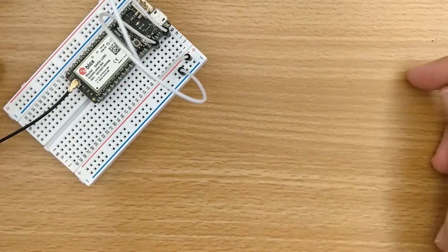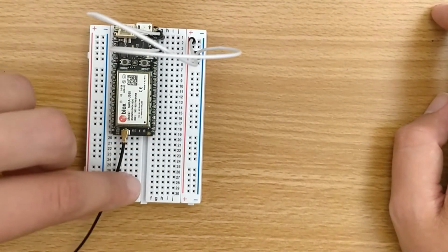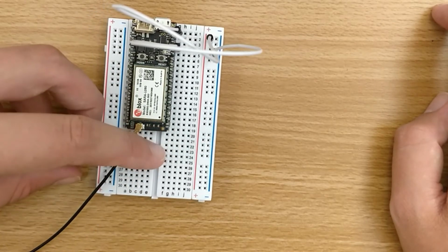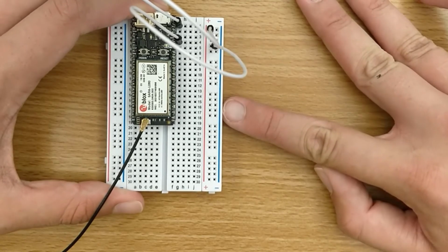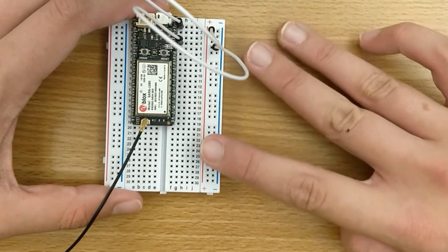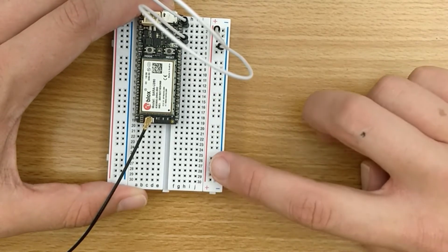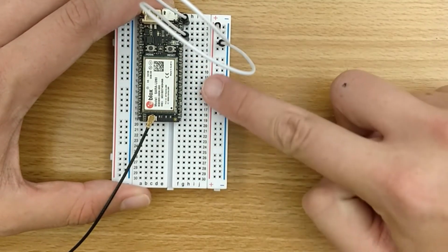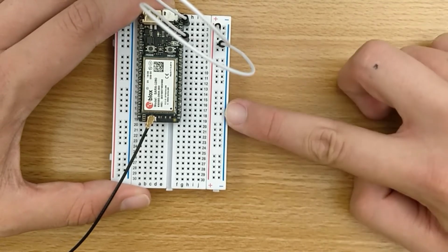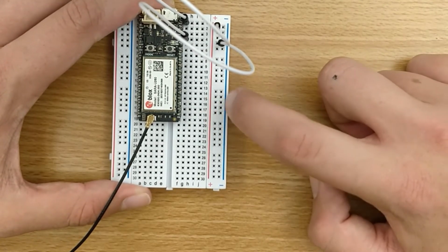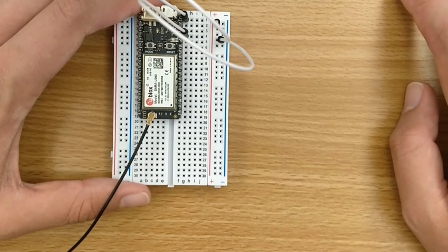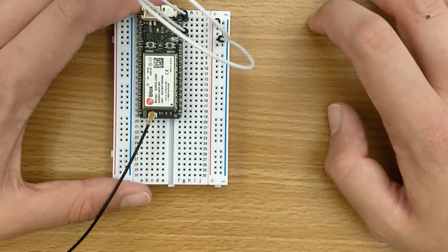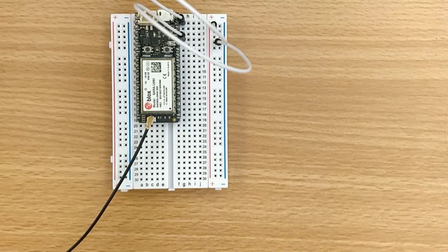Now the reason I'm doing this is although in the main section of the breadboard things in the same row this way are connected, in this side section the connection runs vertically instead. So the idea is everything on this left side next to the red is connected this way, and everything on the blue side is connected, but they're not connected this way. So what this does is it creates a whole column here which is connected to the ground on the Electron, and a whole section here which is connected to the power on the Electron. It'll make our life a lot easier when wiring up the rest of our relays.